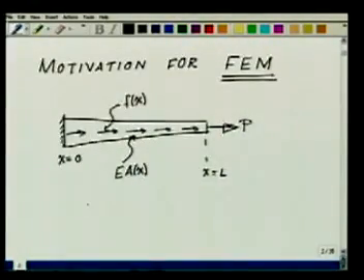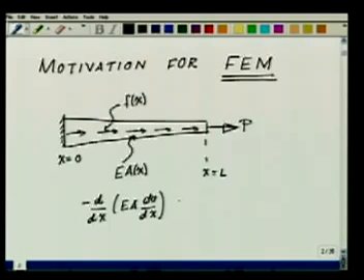So if I wrote the differential equation corresponding to this bar, we have done this enough number of times already, it will be minus d/dx of EA du/dx is equal to f(x) for all x's lying between 0 and L.